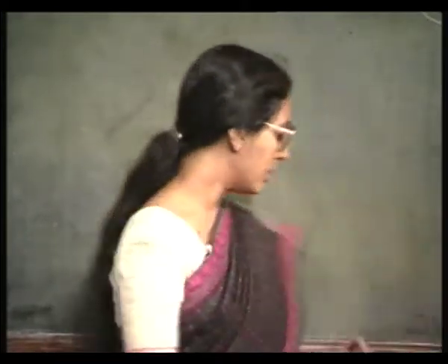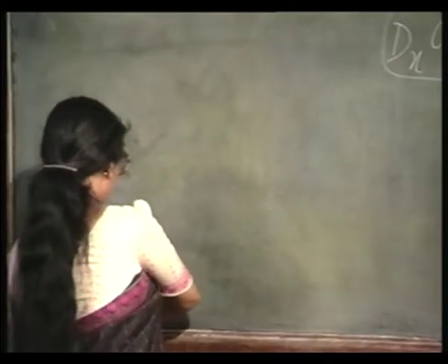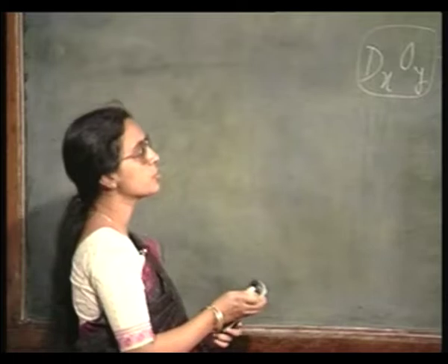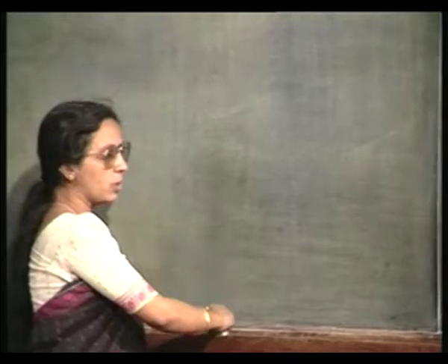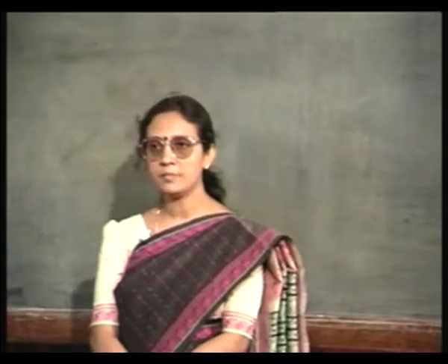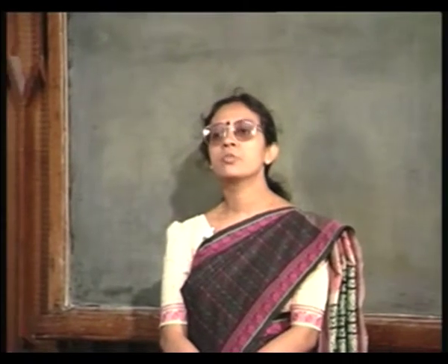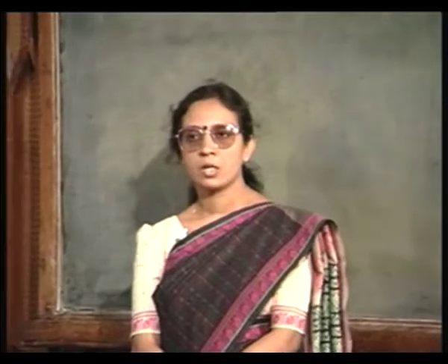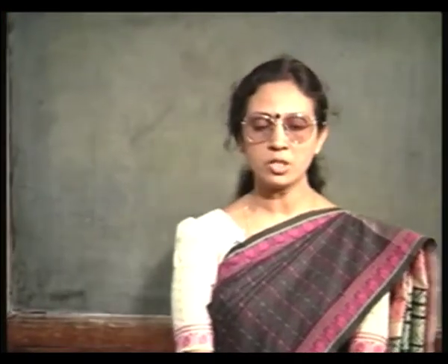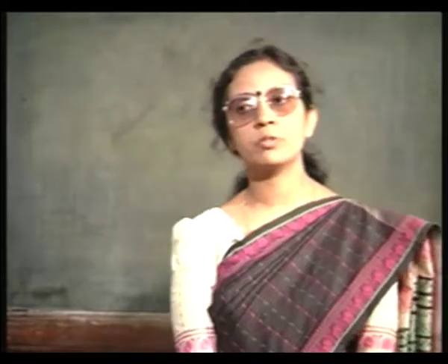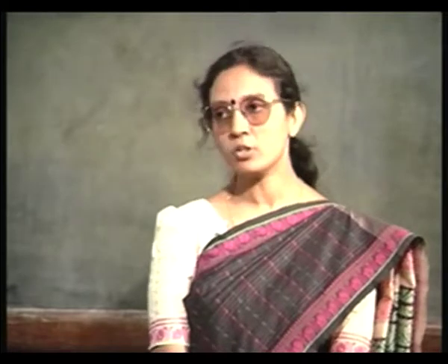Now, let us talk about one of the most important dopant materials in silicon, the only one available p-type material, that is boron. In order to diffuse boron in silicon, what are the things that we should know? First of all, what is the diffusivity of boron, the diffusion coefficient. Now, the diffusion coefficient of boron, of any material for that matter, is going to be dependent on temperature.